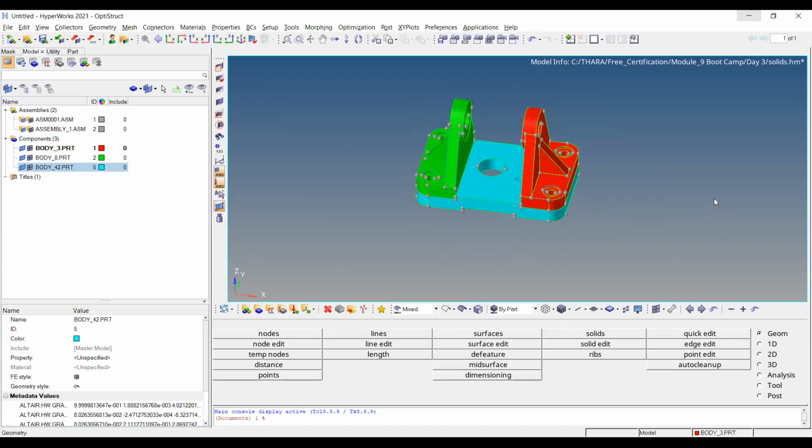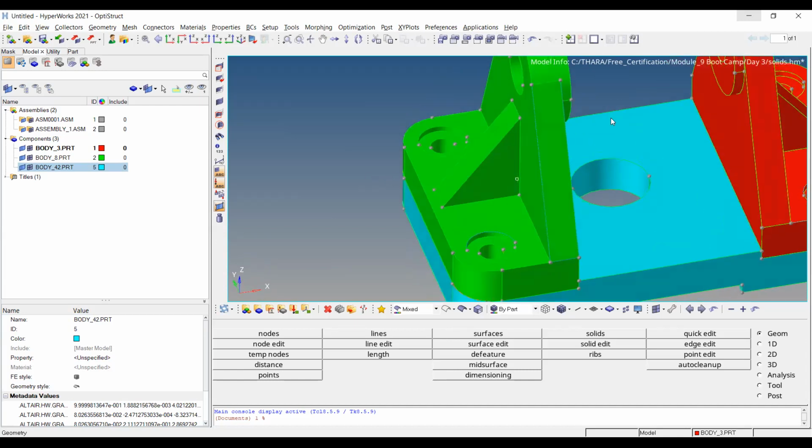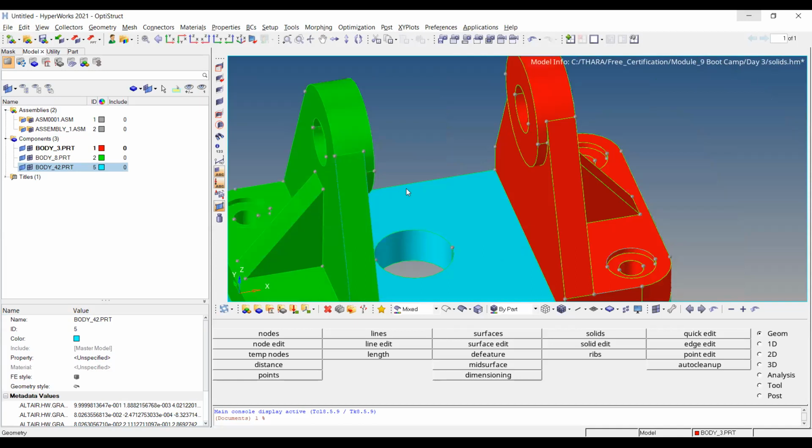This is one of the advantages of using tetra elements. Doing a tetra meshing is easy compared to hexa elements. That time we will just go by creating the tetra elements, apply the same load condition and boundary condition for the respective components, and extract the results. But later, if the extracted results are closer to the accurate results, then we will go by creating the hexa elements. But as I said, it depends on the time. If you don't have time, we are choosing tetra elements.